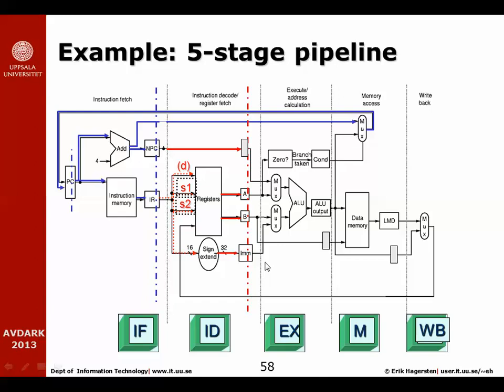That's the end of that phase, and then comes another clock tick, and now all the values stored here will be available. Actually, I forgot to mention an important value stored up here. This is the next program counter value. It's also being latched at this point in time up in this register over here. So we have the next program counter, we have A, we have B, the 2 source registers, and we have the immediate. Now, the job of the next stage, the execute stage, is to put this ALU into business.